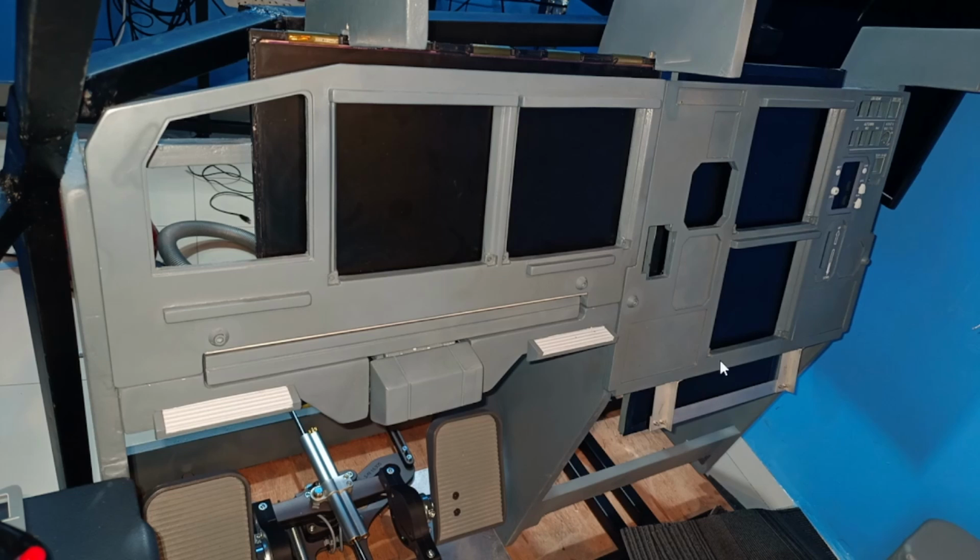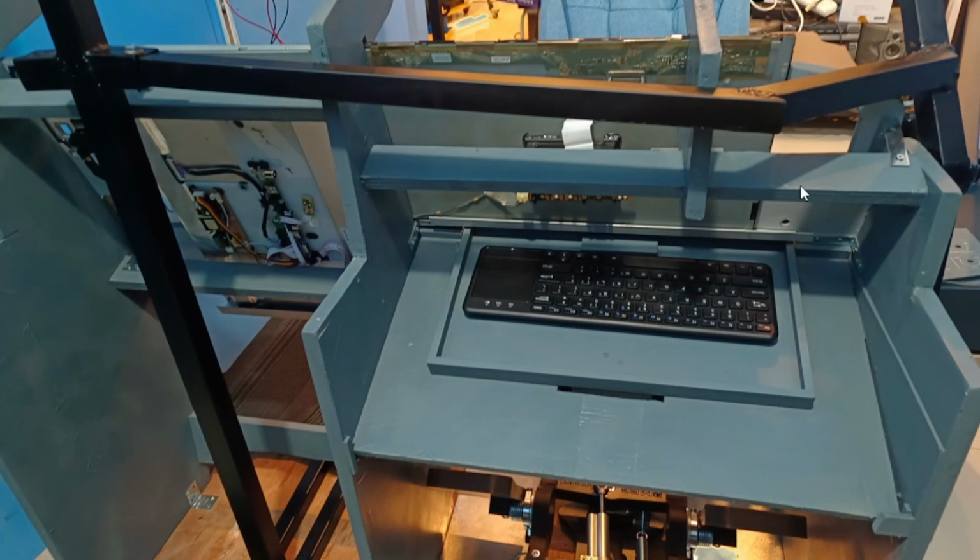You can put a bracket here, and actually the monitor is being sandwiched by the board and the bracket. So from behind, you can see I already dismantled the plastic frame of the monitors, so you don't need the plastic frame. The enclosure basically is gone. This one is also gone. So I just attached the controller board to the back of the panels. Of course, you have to put some isolating material like acrylic or thick plastic to ensure there's no short circuit, because this one is a metal backplate.